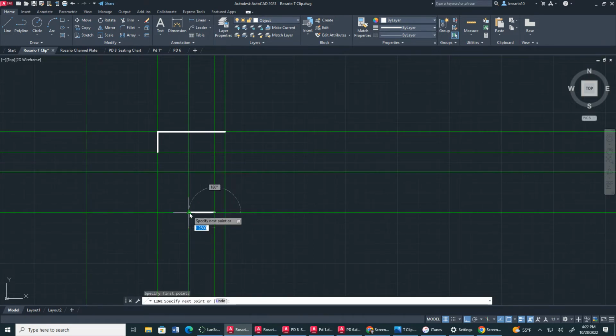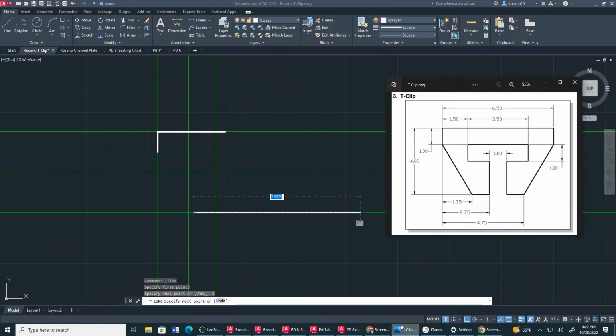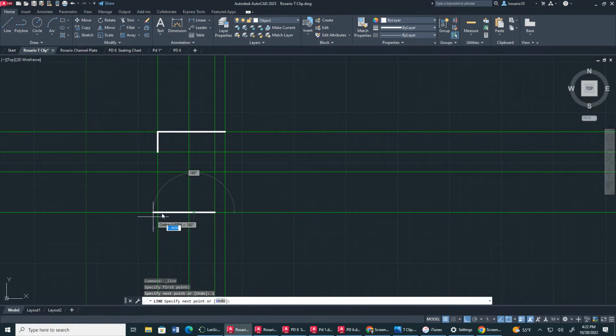Now, a lot of you guys were going over here. That is not correct. We are supposed to be typing in 1. The reason we are supposed to be typing in 1 is because 1.75 minus 2.75 is 1. Now, I'm going to connect it here. Remember, when we have ortho mode on, it's not going to let you snap automatically, but we have our constraints that are going to overpower or override that. Boom, there we go. Now it gets more simple.